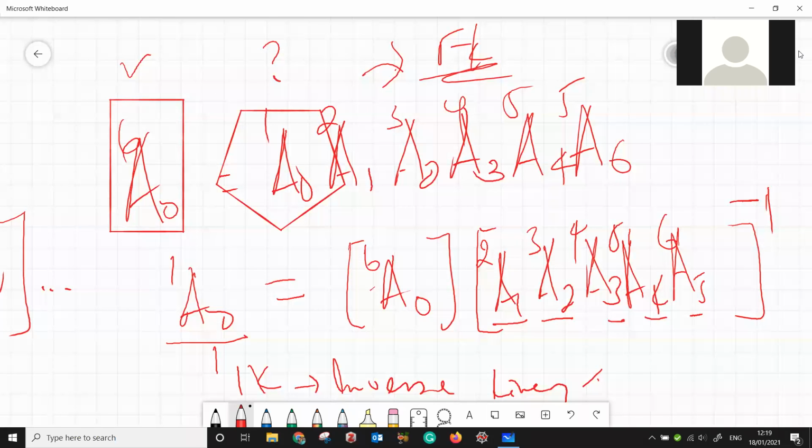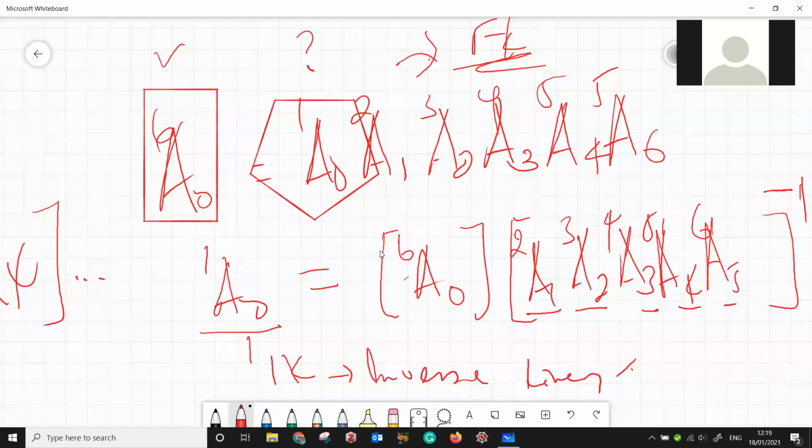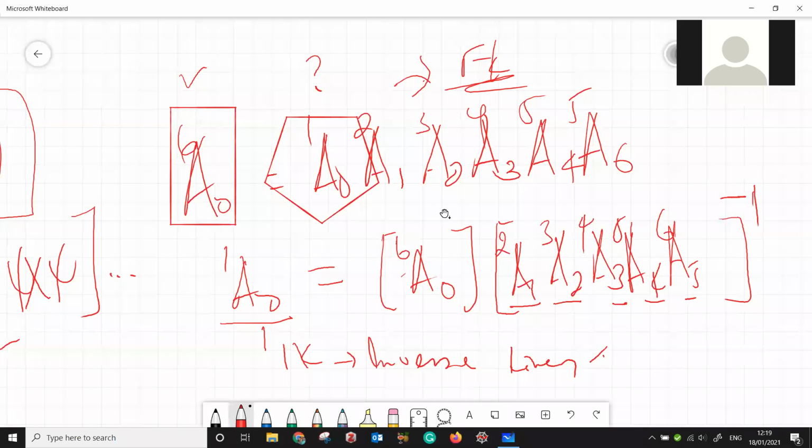But there are so many approaches for inverse kinematics. You can have a geometric approach, you can have a numerical approach. Even nowadays, there are people who have tried to compute the inverse kinematics of the robot using learning algorithms. They train a model from the forward kinematics, and then train it to do the inverse kinematics for each joint variable. That's possible, of course, but it is computationally demanding, you have to export the model with the robot, it depends on the trained model, and it also depends on how accurately the robot is represented in the model. But yes, there are people who have tried that.